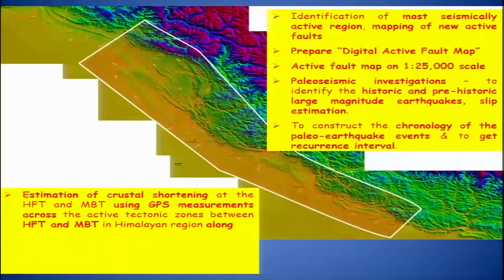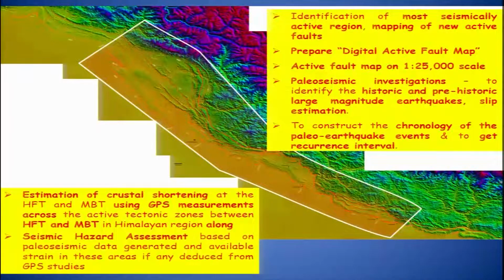We are taking one transect here, another one here, a third one here, and so on, so that we know in which pocket of this region there are chances of a next earthquake. This will be important data to collect to understand and properly evaluate seismic hazard assessment.